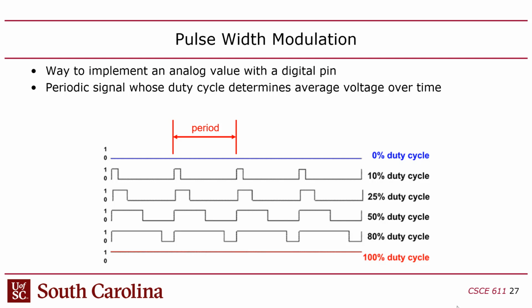Okay. So in other words, if you have a 25% duty cycle now, but you want to brighten your lights, you'll have 25% in this period. When you go to the next period, you'll have slightly more than 25%, right? So this period, rising edge to rising edge, you'll have 25.0001%, right? And then you get to this one and you'll have 25.0002%, right? So the duty cycle can change over time, but it's measured as the percentage over the period of the signal.